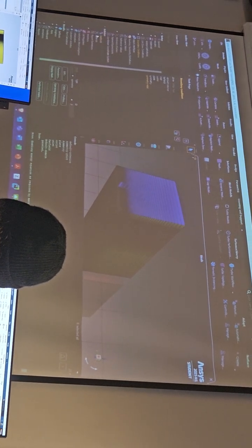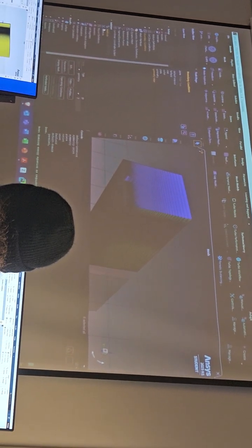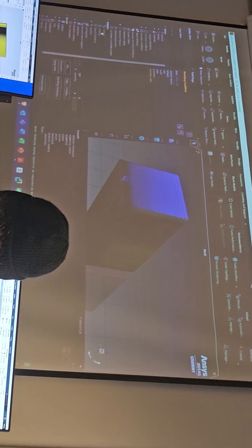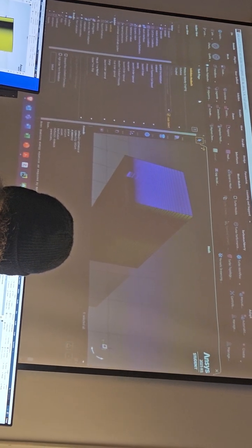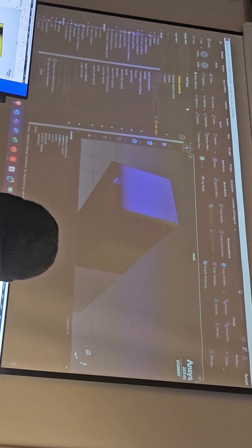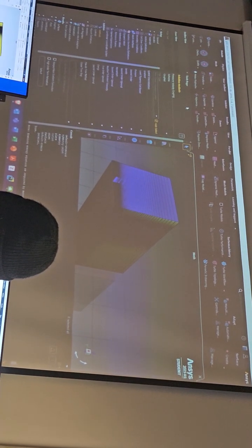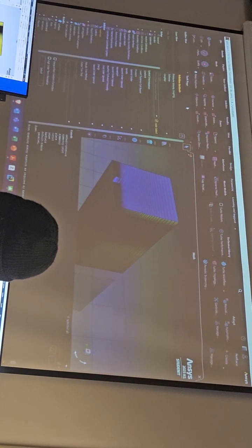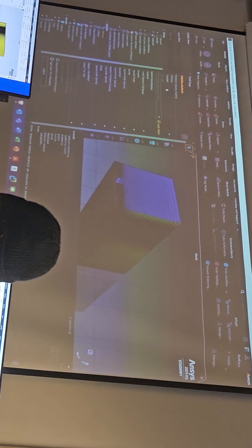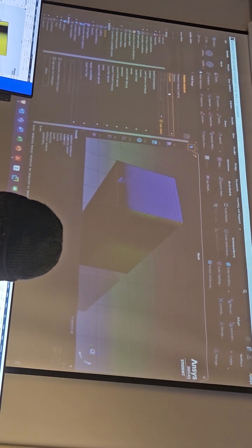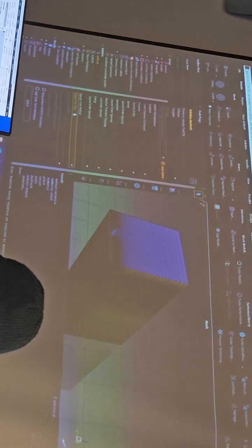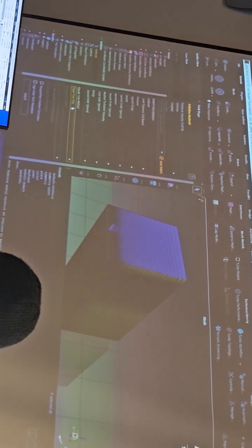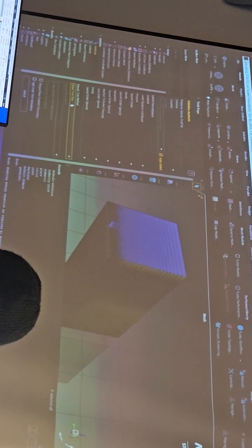Then next thing we can do is in methods. Now we have the default settings that we didn't change last week. So I'm running with this coupled scheme, and there is a global time step. That is, there is a transient term also in the governing equations that you are solving.